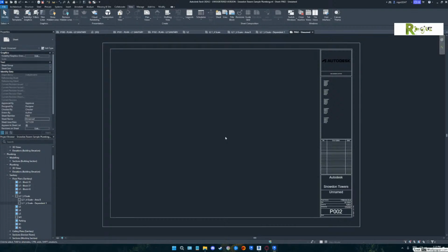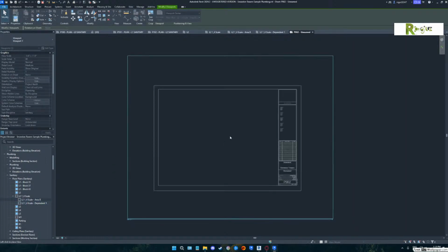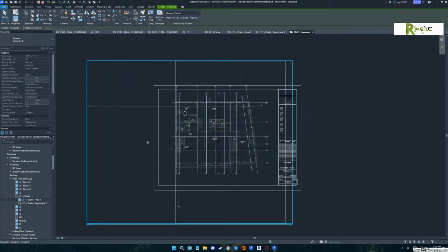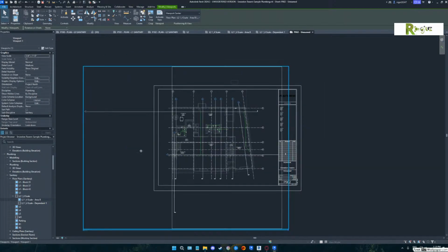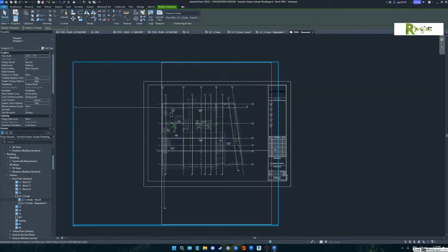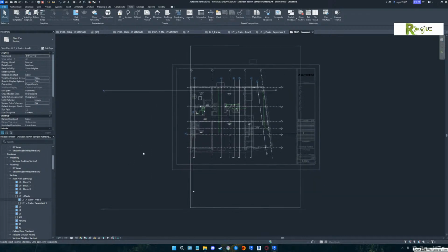Now, if you dragged your area B onto the screen, you would find it would fit in the X direction, but not so good in the Y direction. Right? Yeah. Now, a better way to do that is to double click on that view and suck that crop boundary to inside the title block.